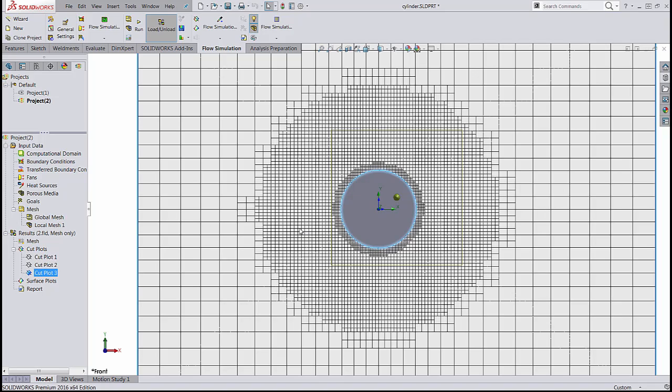because all the changes are happening behind the object as compared to in front of it. Similarly, if you're trying to simulate free convection, where there is more movement of the fluid above a part due to buoyancy effects as compared to below it, having a uniform mesh around a part is counterintuitive. As compared to that, if you have a forced convection, maybe where you have a part and you're looking at the temperature distribution around it, then this might be a useful feature to have.